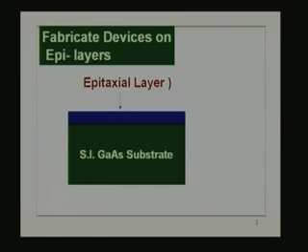layers on the top of the semi insulating substrate. So, that is the epitaxial layer, which ultimately we said will be the one which we use for making the devices. Now, when you want to make these devices in integrated circuit, what you need is not merely the ability to make device, you must be able to isolate the devices from one another in integrated circuits.